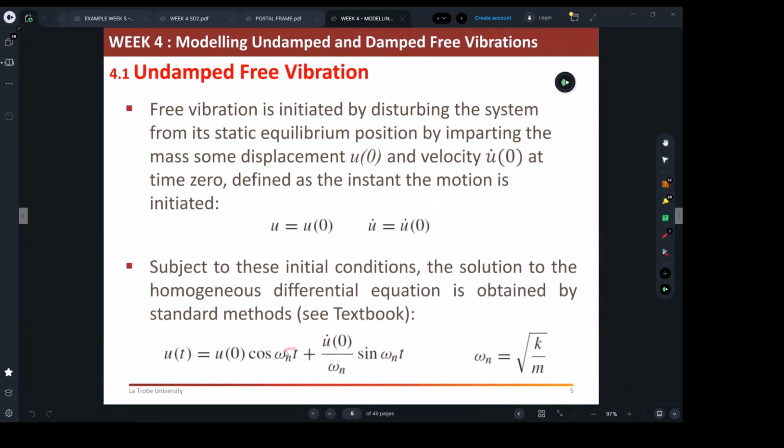So in the equation here, instead of omega n, they had this figure, root square k over m. Their engineers decided to call the stiffness over m, root square, as omega, which is what you all know from physics. It is the natural frequency. So this is the natural frequency of the system. Omega is the natural frequency of the system, which is defined by taking the root square k over m. From where it came from,